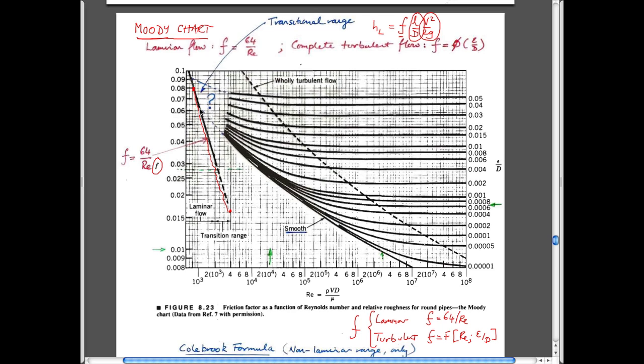So in other words, if you start off here, and this is kind of undefined area, but if you drastically increase the Reynolds number, and your pipe has a particular roughness. So if you have a very smooth pipe, and you keep on increasing the Reynolds number, then your experimental results will just define a line as you increase the Reynolds number, which will give you this pressure loss. You'd measure the pressure loss, and you'd convert that into this friction factor, right?